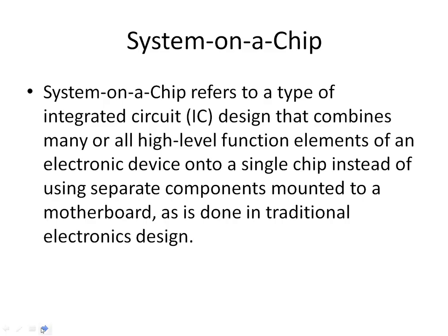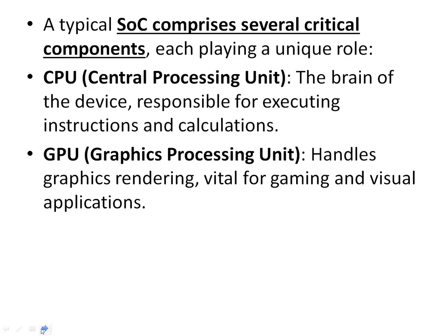A system on chip, SoC, refers to a type of integrated circuit design that combines many or all high-level functional elements of an electronic device onto a single chip, instead of using separate components mounted on a motherboard as done in traditional electronic design. A typical SoC comprises several critical components, each playing a unique role. The central processing unit is the brain of the device, responsible for executing instructions and calculations.